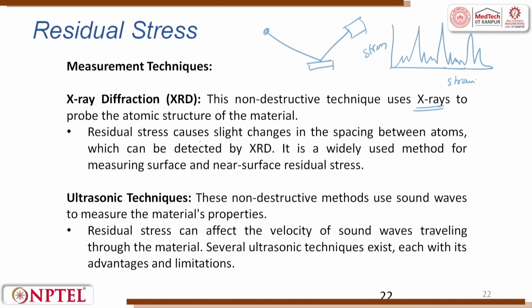Here what they say is it causes a slight change in the shape, the spacing between the atoms, which can be detected by XRD. This can shift the peak left or right, or it can widen the peak, or it can reduce the height of the peak.